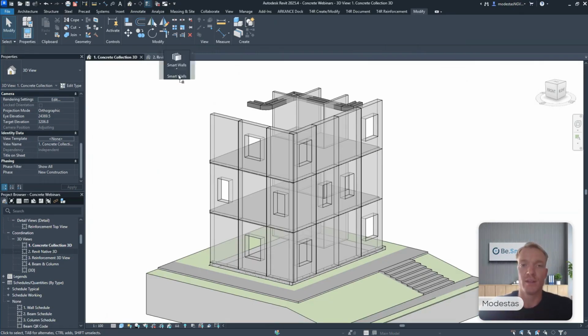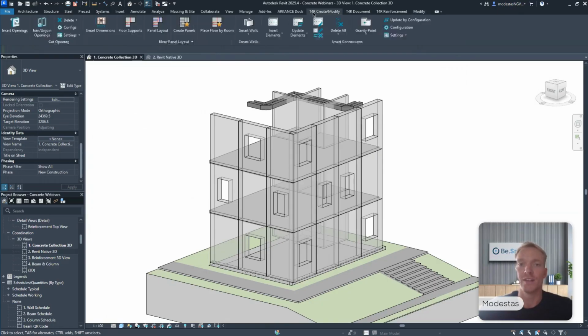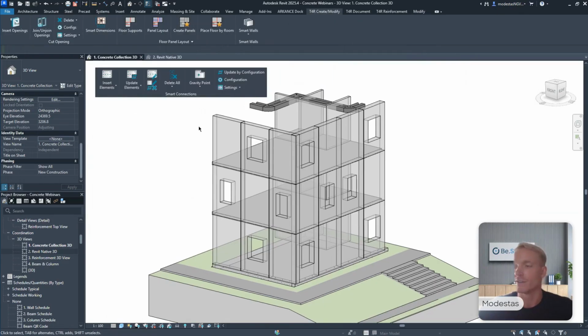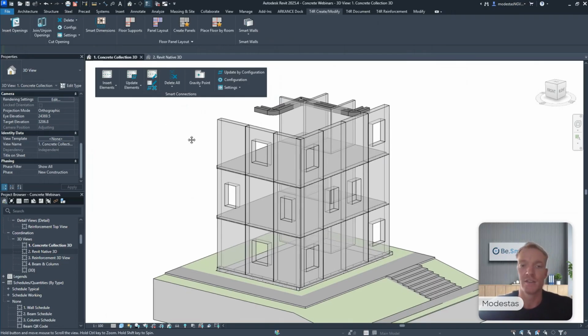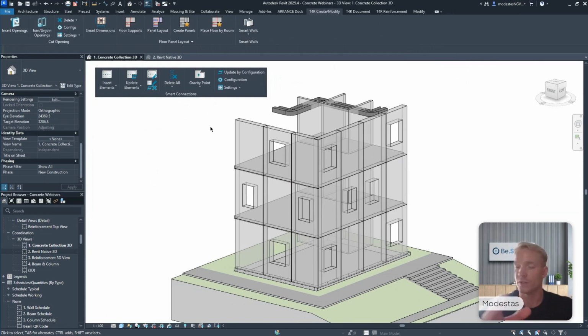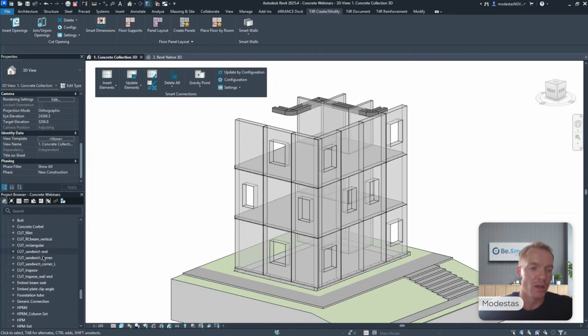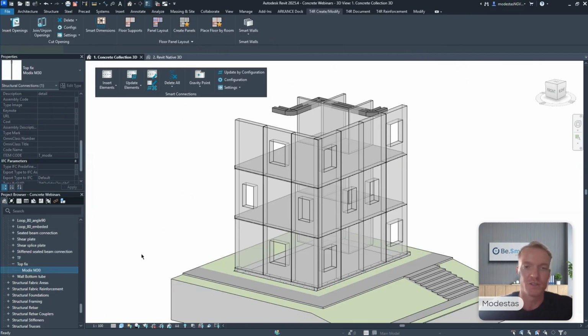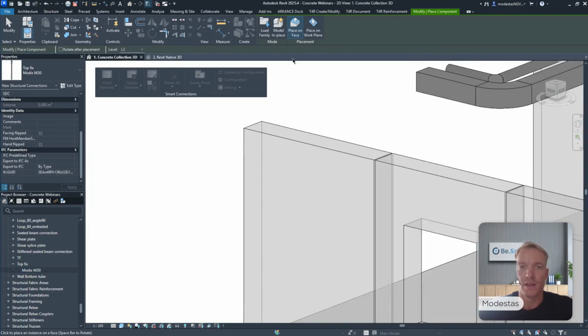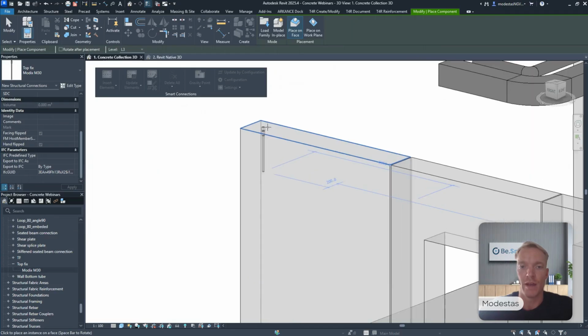Now, once the walls are split, another important thing is to place the details, place the connectors, anchor points, some loops or connecting elements between the wall panels. And that's also a time-heavy task for you to do if you are using Revit only itself, right? So if I want to place multiple different elements on the panel, firstly, I need to find the element I want to use, right? So in this case, I'm using Project Browser, and I know that I have some lifting points under the structural connections categories. And I can start placing them on face of the wall panel.